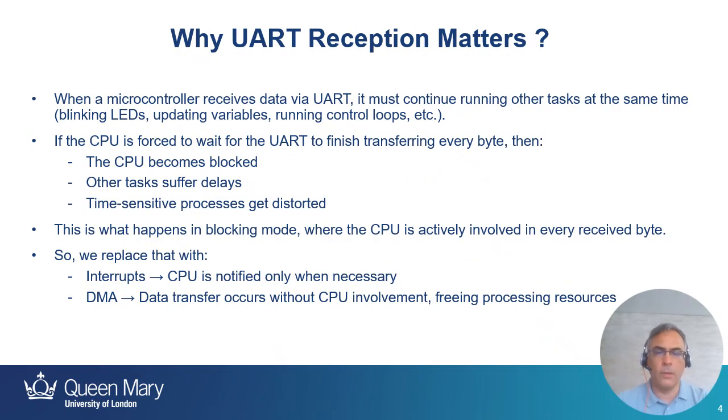So why does UART reception matter? When a microcontroller receives data via UART, it must continue running other tasks at the same time. Example, blinking LEDs, updating variables, or running control loops. If the CPU is forced to wait for the UART to finish transferring every byte, then the CPU is blocked. Other tasks suffer delays and time-sensitive processes get distorted. This is what happens in blocking mode, where the CPU is actively involved in every received byte.